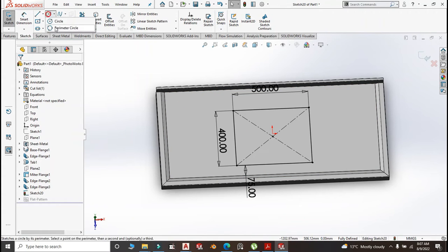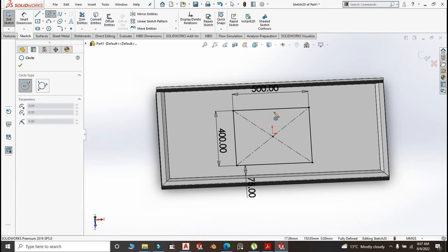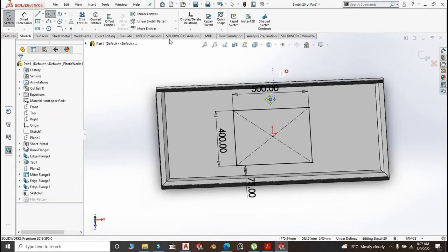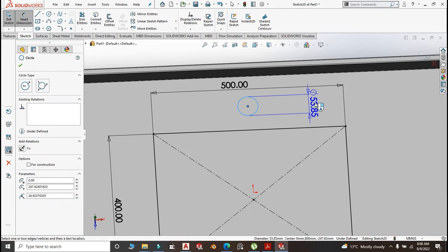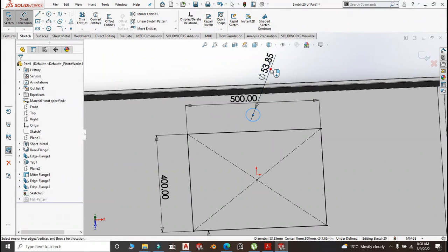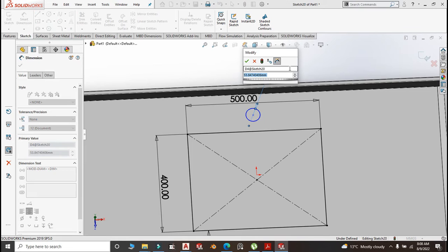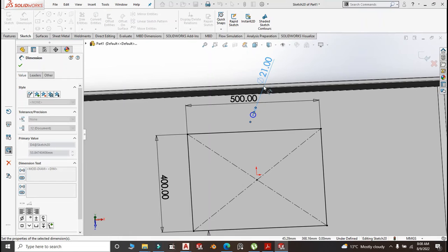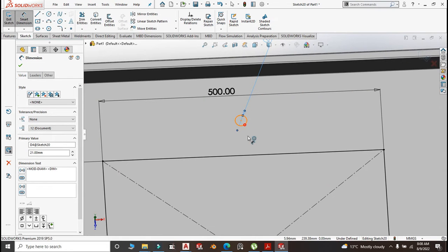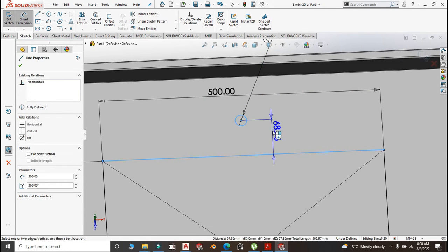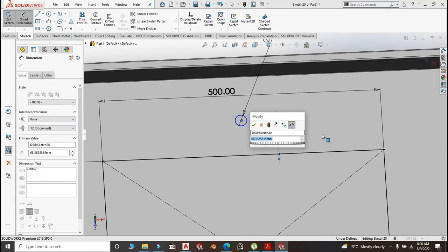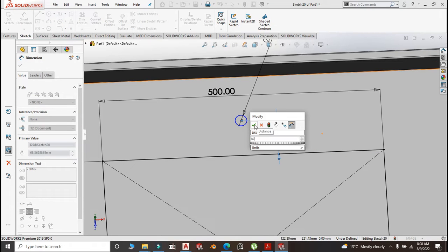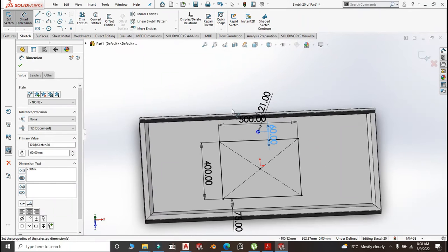Okay, create a circle, snap it from the origin. This is for the opening of the top. Smart dimension, the size. I told you most tabs have a diameter of 20, so make it 21mm. Don't want to interfere with the threads of the tab as you are inserting it. Shouldn't be very tight. This should be 60mm from the edge of the sink.